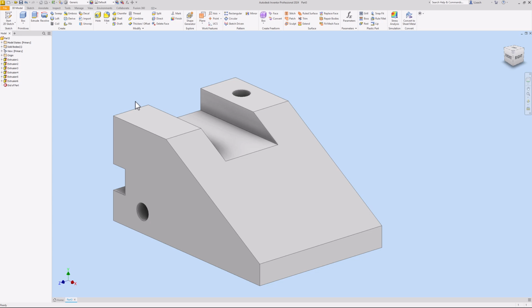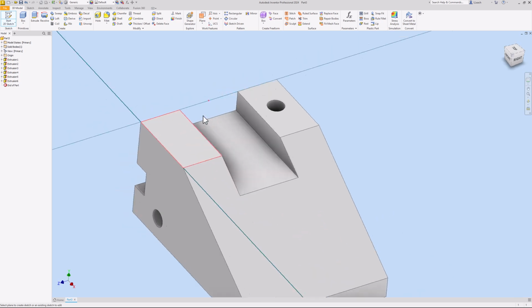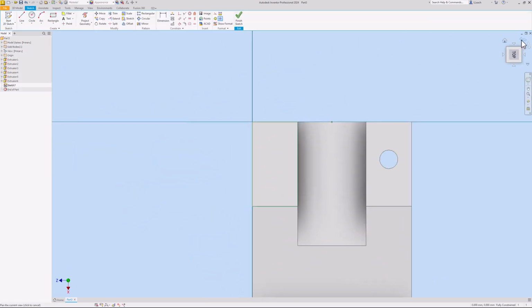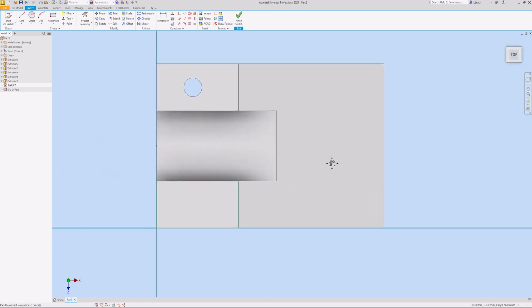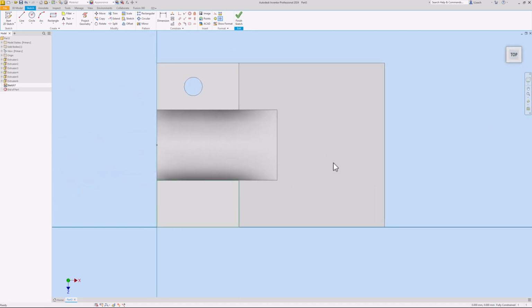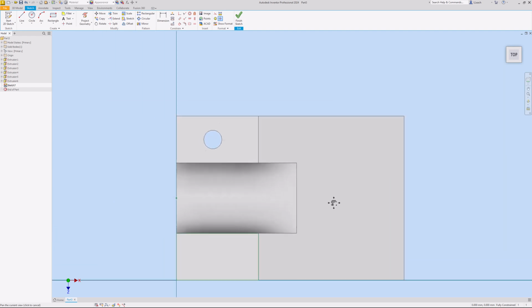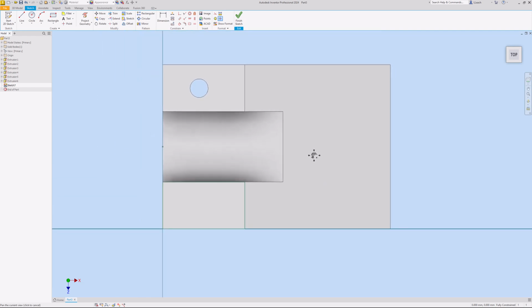So now we just need to make that little side angle piece. So how do we do that? Oh yeah, start 2D sketch on this top face here. I'm going to rotate it again counterclockwise. Center this thing. To center it, if you have a wheel mouse, I just held down the wheel of the mouse and just kind of drag it around where you want it.